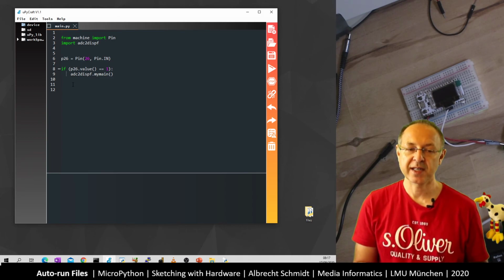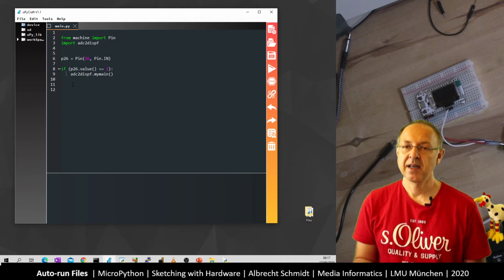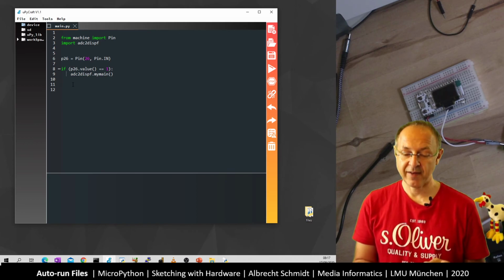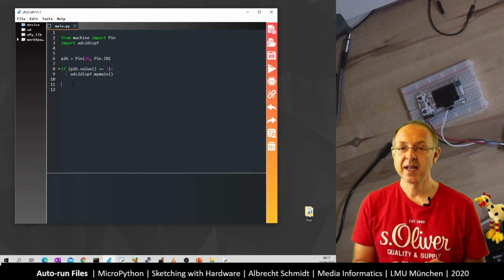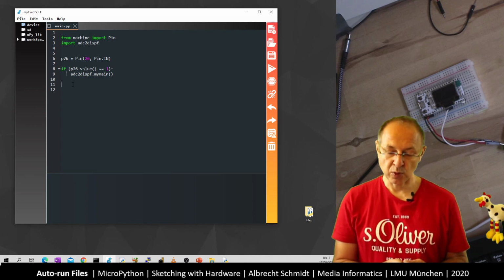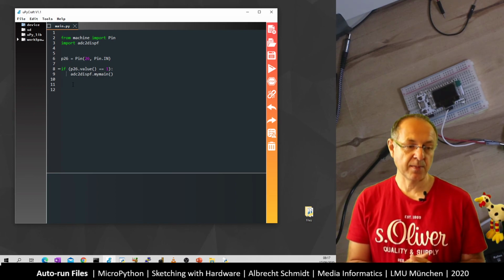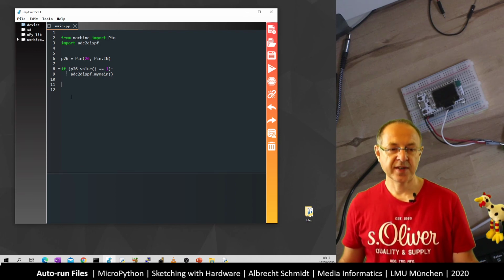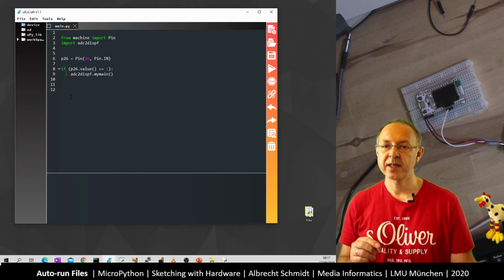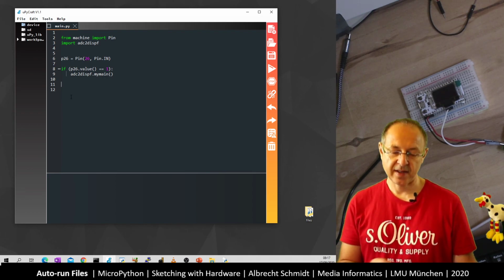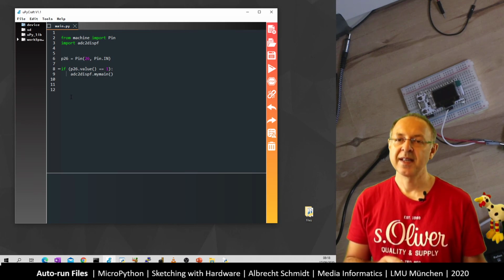You can do a lot of things like looking at local pins. You could have a switch which selects between different programs. You could have a sensor that selects between different programs. So in this main function, you can decide what happens during the boot process. And we will look at some point how you can use the network variables to decide which program should be run. And I think with this, you should know now how to write a program to make it into a module which you can call, and then have a main function on the chip that's calling it.